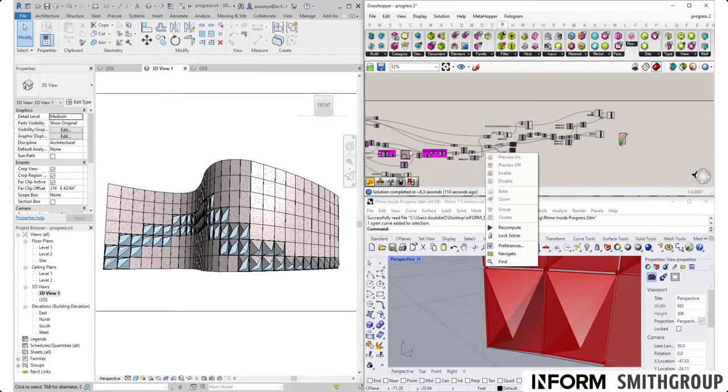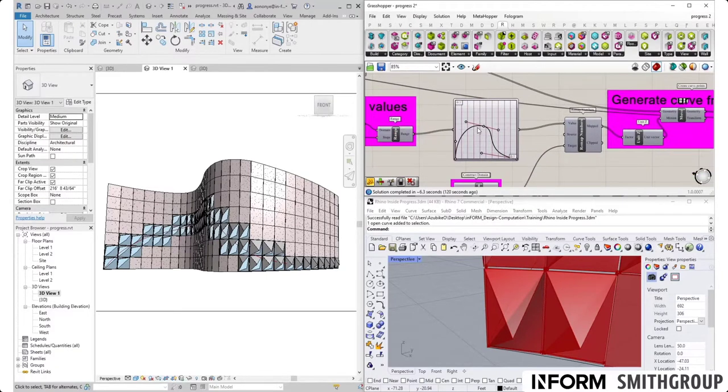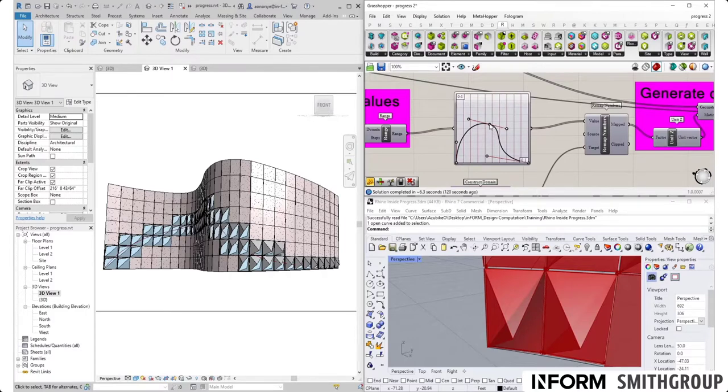So if you had to adjust this curve, the attractor curve that we had before, you should see the panels change. And now you can, obviously in a real project, you won't have variations in all of these panels. You have maybe 5 or 4 standard panels for ease of construction. So an assignment to you is, how would you standardize using Grasshopper?